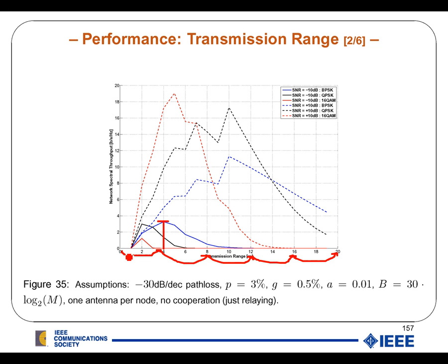If we now increase the signal to noise ratio going to 10 dB, things change immediately. Now the maximum is here. And that is achieved if we transmit using 16 QAM. That means we transmit frames which are much shorter because, of course, the performance is now determined by the collisions and not by the frame error rate due to errors on the physical layer, but rather by errors at the medium access control.